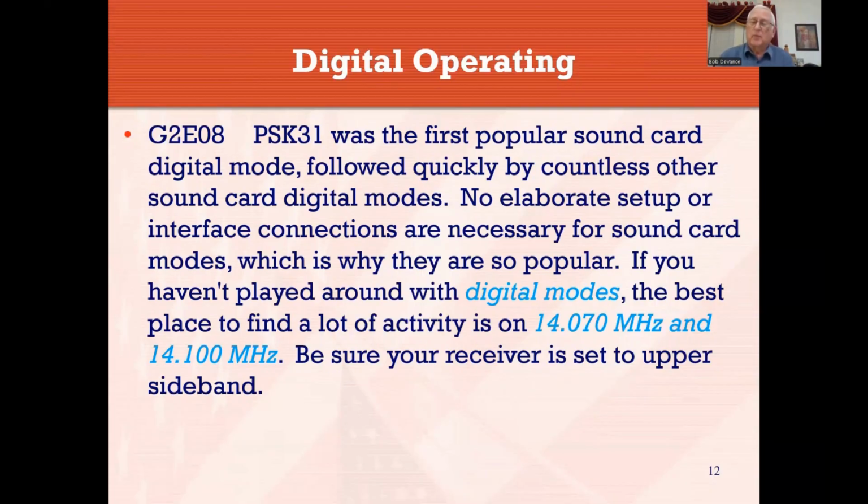So it's relatively simple. You could actually do a completely passive box for that with no amplifying agents, no active agents, no transistors or anything like that in it, all just passive components. The chief being two little transformers. You would use two one-to-one audio transformers to isolate the inputs and the outputs of the sound card from the radio.